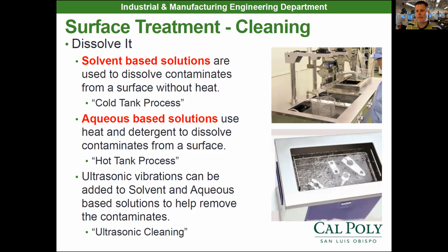So a solvent tank, if anybody's ever had a parts cleaner or parts washer, has some sort of solvent-based solution in it, and you sometimes can just dip the part in there and the solvent takes care of it. Sometimes the part's a little bit dirtier and you might need some sort of mechanical agitation to take care of the dirt or the particles on that surface. It's really all that's on that surface are some sort of other particles other than the base material.